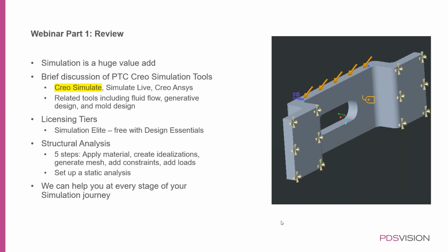We have generative design in Creo as well, which allows you to apply certain loads and constraints and then generate geometry that will lower stress in that scenario. Generative design is really cool because it can be used with 3D printers to generate geometry that would not be really manufacturable using traditional methods.